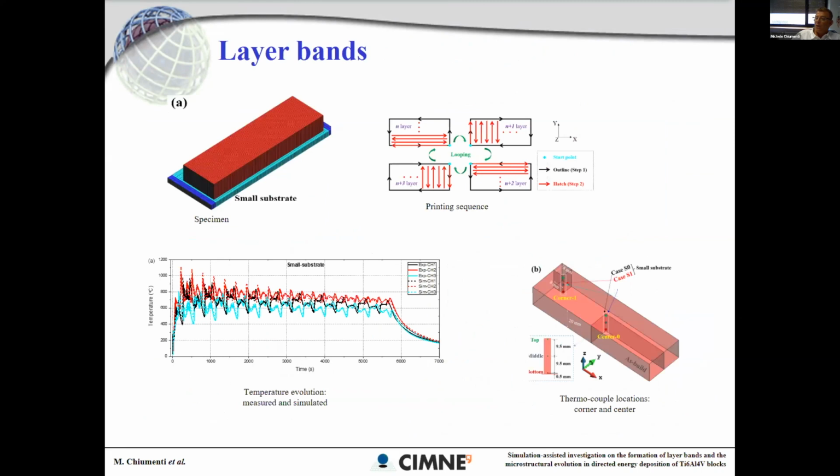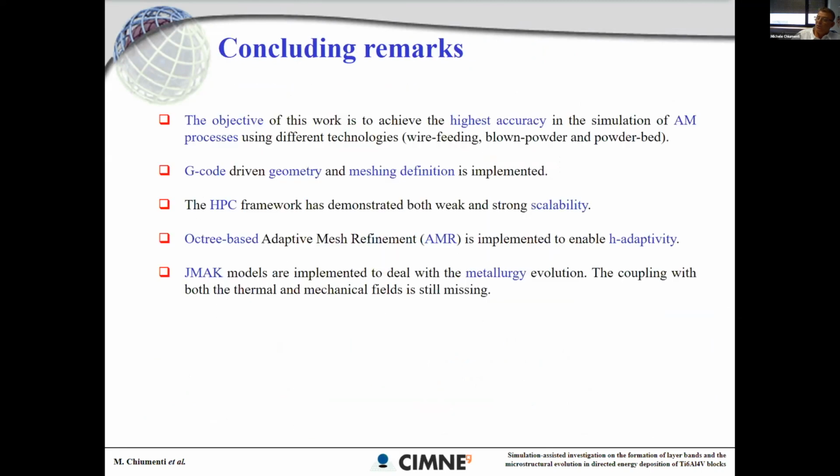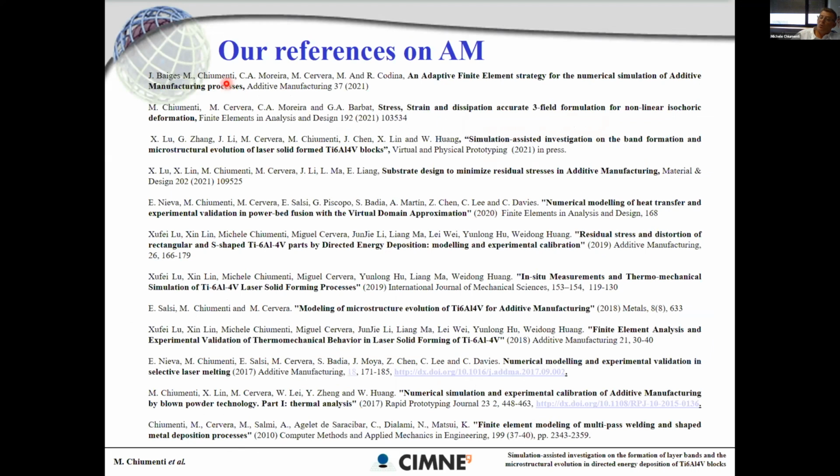I don't have the time to enter into detail, but if you have a look at the first publication in this list, we define a method to retain the information of the fine mesh in the coarsened mesh. This is a correction after the extrapolation of the value to the coarsened mesh, to retain the same configuration as you had using the finer mesh.